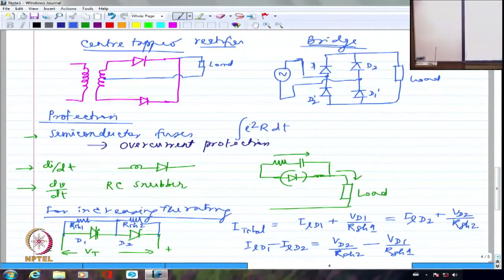And the rate of charging of the capacitor in this case is a constant, because the current is constant, right? So you are going to have a linear rise in the voltage, which will also make the voltage across the diode not go up drastically. So you are essentially averting any chance of the diode breaking down because of the sudden increase in the voltage. That's what happens, right?